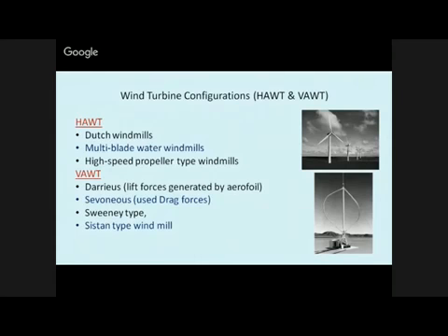As far as most big-size wind power turbines are concerned, the horizontal axis is the preferred one, because manufacturers have developed them like this, and most of the key players across the world, Gamesa, RE Power, Siemens, and various other big manufacturers, are manufacturing in terms of megawatts. Even for a single turbine, earlier it was 1 megawatt, now it is 2 megawatt, and people have gone up to 3 to 4 megawatt, because the commercial viability is there.